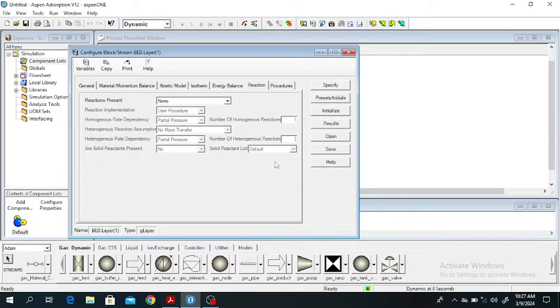So the bed specification, I have information about the bed specification, meaning what will be the isotherm parameter for methane, carbon dioxide, what will be the radius of the adsorbent. So in this case the adsorbent is the activated carbon, so we will use the information about the adsorbent and the adsorbate, which means the components.